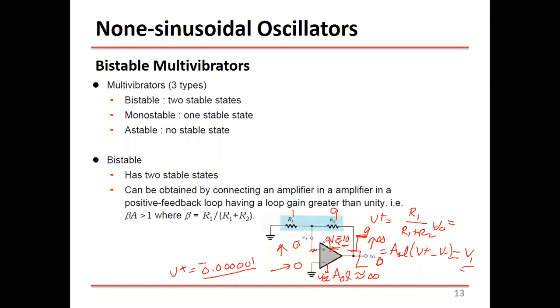So even if you build a circuit like this using an operational amplifier with positive feedback, you cannot predict the output. The output might hit the maximum or the minimum. It's something random, depending on the built up noise at the positive terminal. So this is considered a bistable circuit.